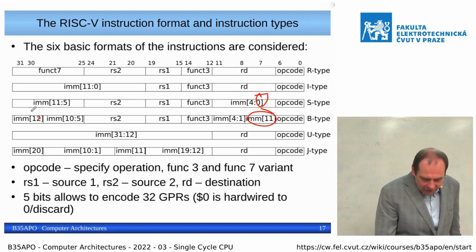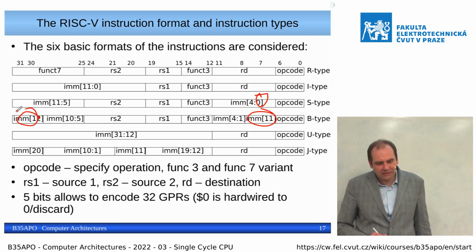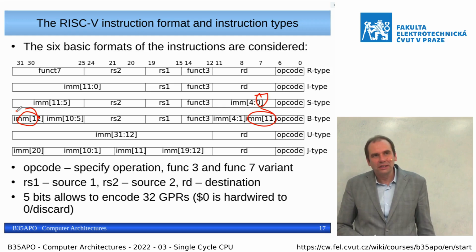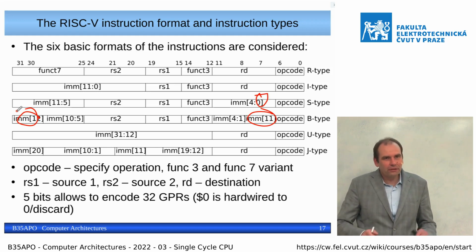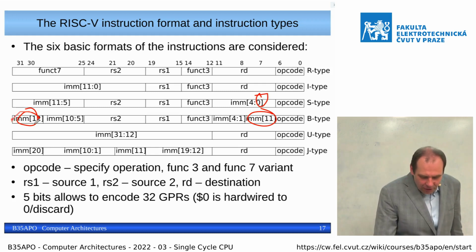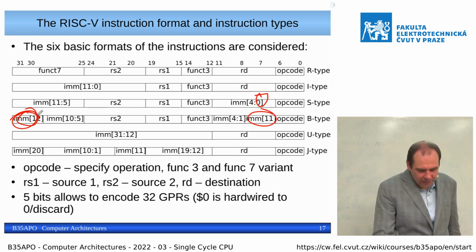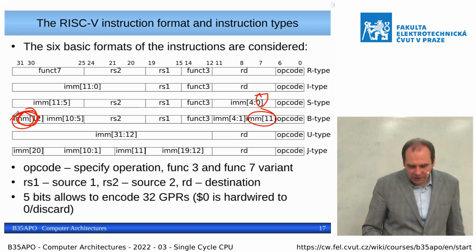And bit 12 is kept as the most significant bit, because this bit is needed to extend the sign, and for the reasons that there is a limited logic gain or fan out of the gates, they decide that this bit will be optimized and kept for all instructions as the most significant bit, the bit which is sign extended over some other area.